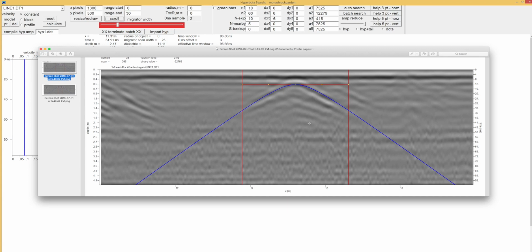Now the goal is to get this black center dot at the top of the reflector, so where I've put it now essentially. The innermost two points, these ones here, need to be put on the white section, just outside of the black section of the reflector where our center one is.